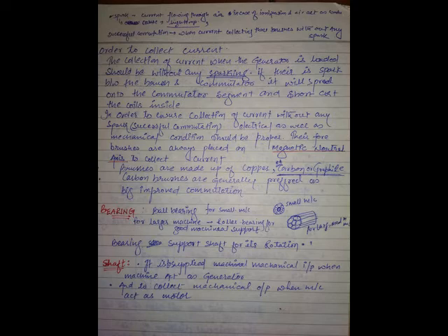If you place here and here, for example, what will be the voltage? This is maximum, this is minimum, 0. So let it be 1 volt, this is 0. So what is the total voltage? 1. If you place one coil side here, and instead of this, place the other here, you will get maximum plus maximum. So how much will you get? 2 volts.